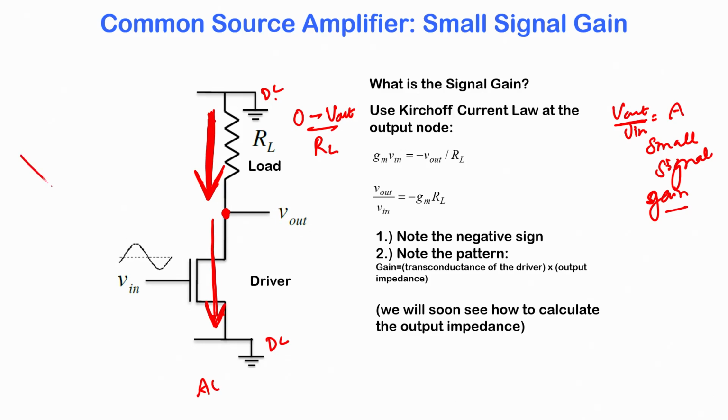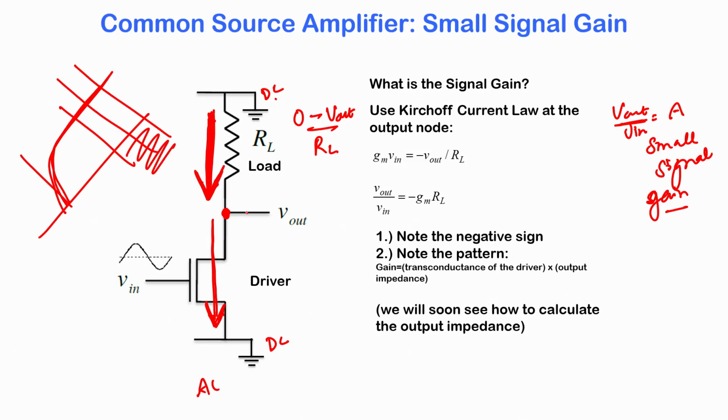If it is an ideal MOSFET in ideal saturation, there is no channel length modulation. Would a fluctuation in V out, or in the drain to source voltage, cause any current variation? The answer is no. Therefore this V out does not contribute to any current in the MOSFET.